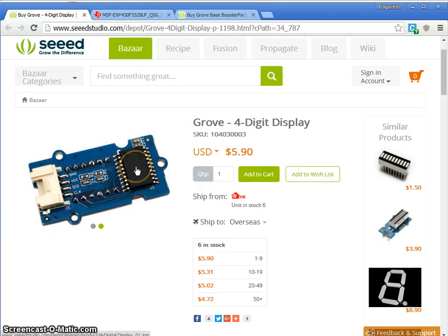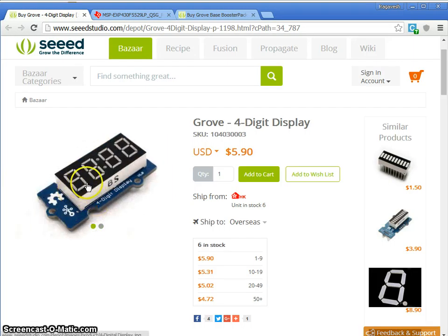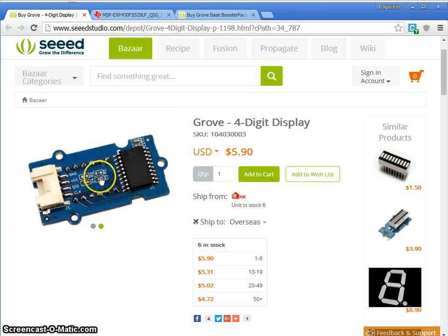It has an IC, and you may notice here we have 4 7 segment display. If you look at the 4 7 segment display, basically it has about 12 pins in the module, like 3 plus 3 is 6, and here 12 pins. If you connect these 12 pins to the microcontroller, first of all the number of IO lines is going to be very high. So we use this display driver.